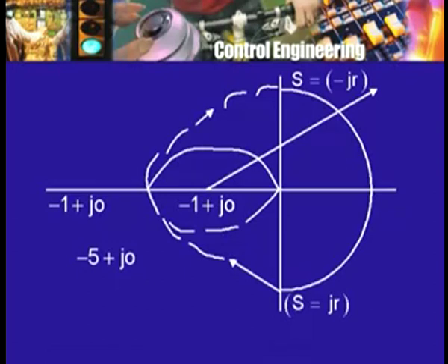So, this is a conclusion that we can draw if the image of the Nyquist contour goes through this point minus 1 plus j 0. The conclusion is that there is an intersection, in the root locus language, of the root locus with the j omega axis, or in terms of characteristic polynomial roots, there will be roots of the characteristic polynomial on the j omega axis. And what will be the value of k? Well, what was the original value? The double of that will be the value of k. So, you can think of it as some kind of a critical value of k.